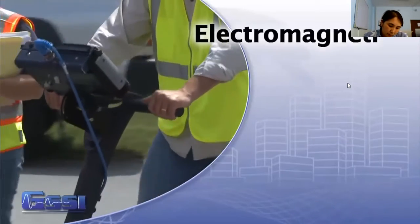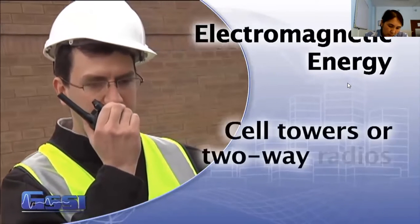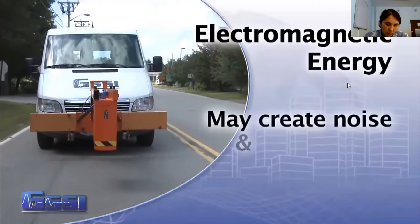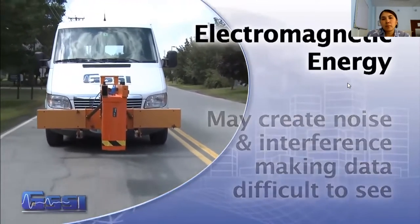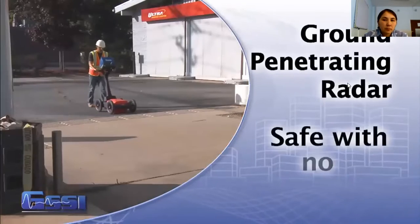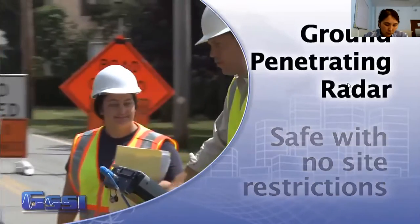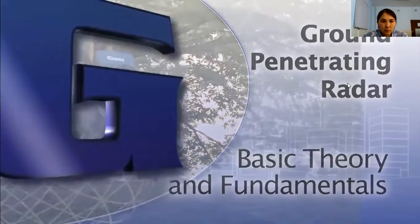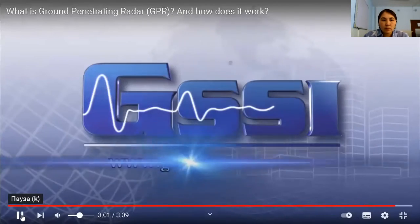Lastly, remember that GPR is electromagnetic energy. Other sources of electromagnetic energy, such as cell phone towers and 2-way radios, may interfere. These will not cause any damage, but may make it more difficult to see deeply into concrete or soil. In addition, unlike X-ray or other technologies, ground penetrating radar is not harmful and has no site restrictions associated with use. This brings us to the conclusion of the theory and fundamentals of ground penetrating radar. For more information on data interpretation and specific applications.